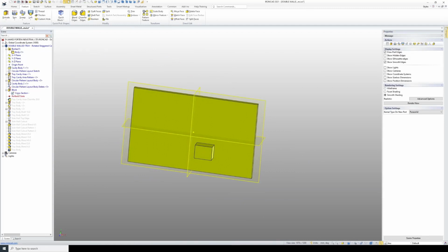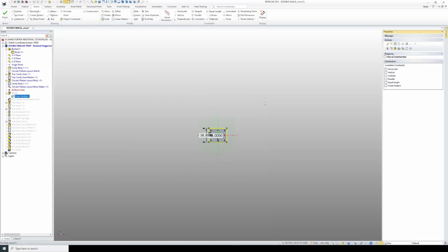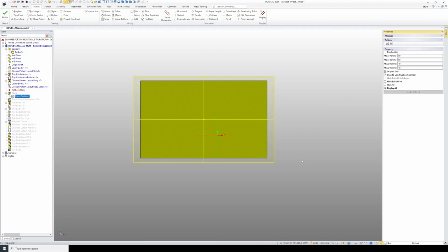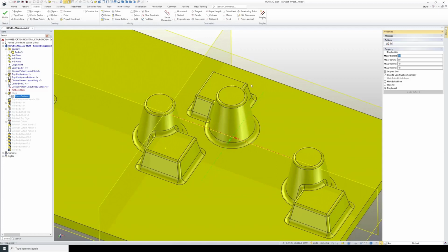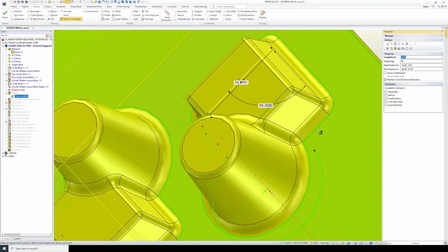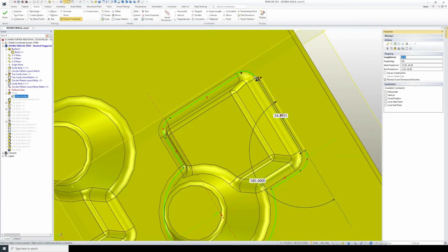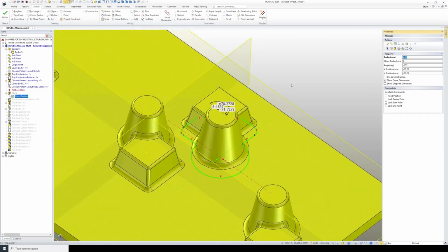So now I want to edit the geometry of that sketch. So edit the sketch itself, and I'm going to delete that existing geometry. And on my right here, I want to display the rest of my scene. And now I'm going to project the outline of that pattern body. So project constrain, and I'm going to select these edges here. And select the tool again to complete it.